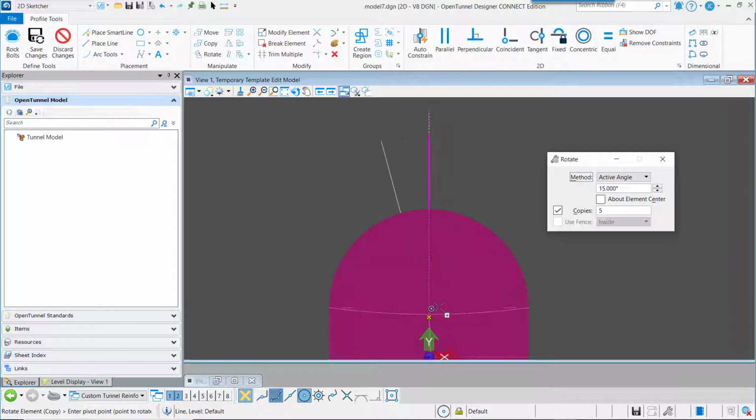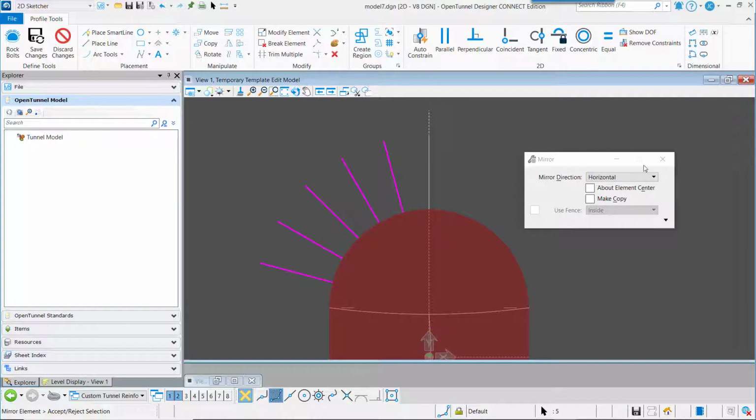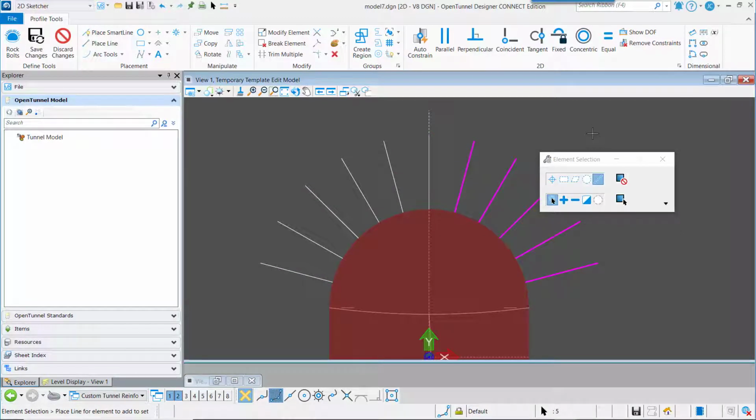Okay, so just go on the circle and snap. Here, and accept. And it places the different bolts around the circle. Then we have just to mirror copy the different bolts. And make a mirror copy vertical on the other side. Here. Okay, now it's drawn.